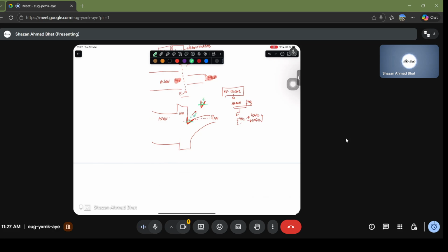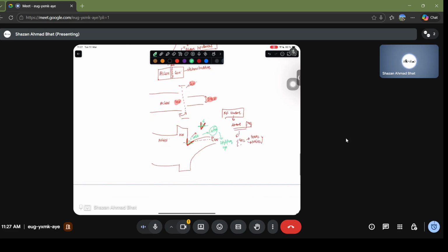This is called the two-dimensional electron gas. That means the electron is able to move in a two-dimensional fashion only, and it's confined in one direction. And that basically gives you a super high mobility, and it gives you a high frequency operation. Okay, and these devices work in microwave regions.